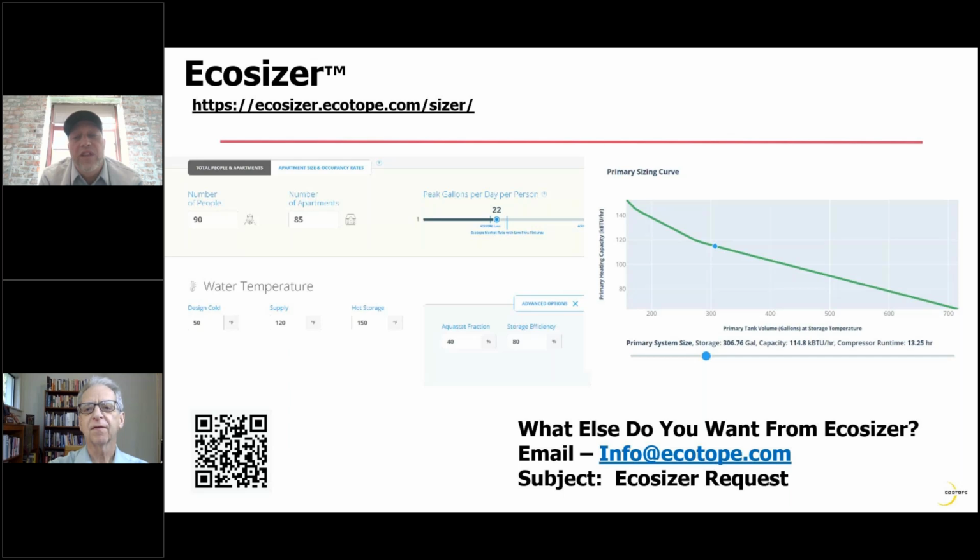Yep. And one thing I would say, backing up there for designers, typically the way that we use that curve is we'll establish our capacity at design. So pick your design temp, 24, 23, 19, what you want. Then you look at the output of your heat pump plant, and you start there with the capacity, and then you move that bar until you match that capacity. And then what's left is your storage. You want to make sure you've got at least that amount of usable storage. So that gets you through your morning rush when everybody's taking showers in the building.